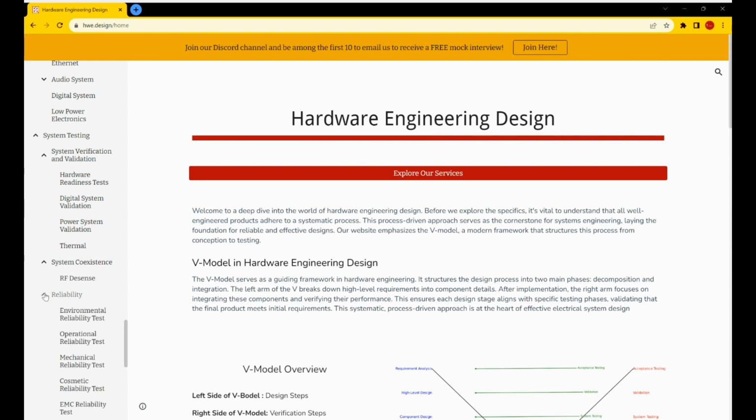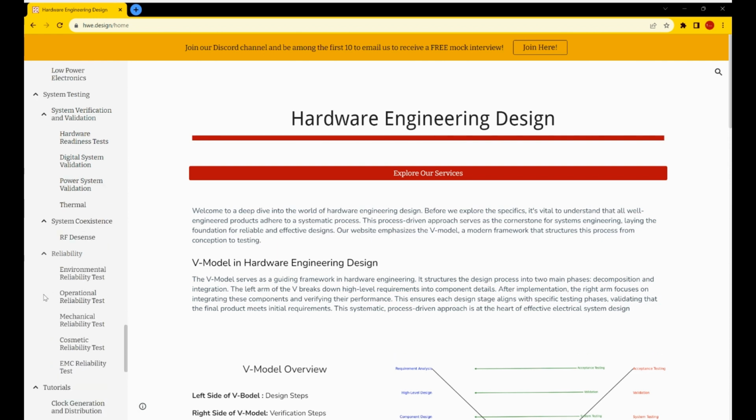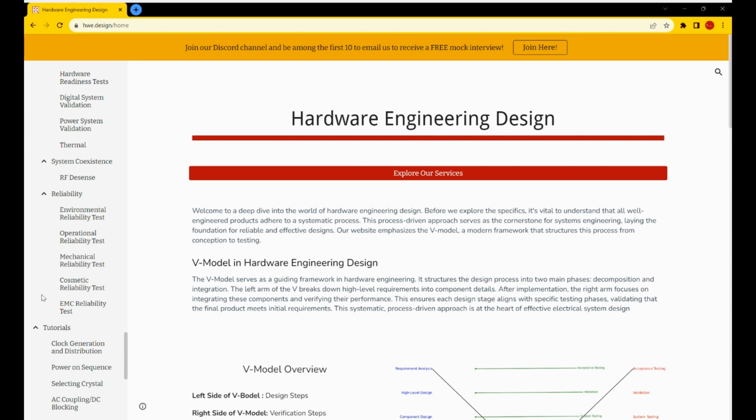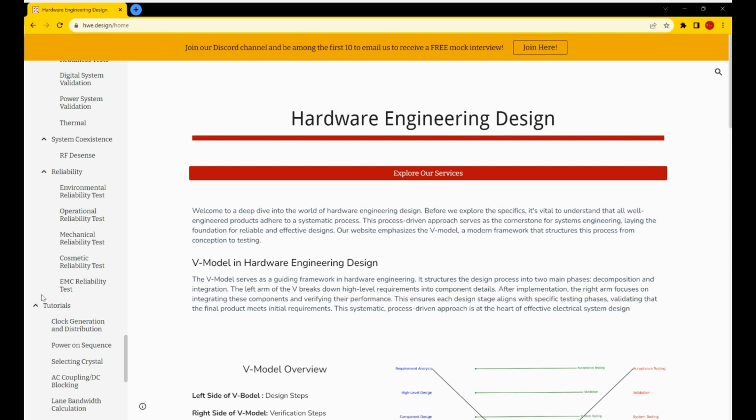Once all these tests are done, we also need to understand how our product endures against environmental factors such as high temperature, high humidity tests, long-term operability tests, mechanical reliability tests such as vibration or drop tests, scratch tests, and lastly, some radiation FCC rules.